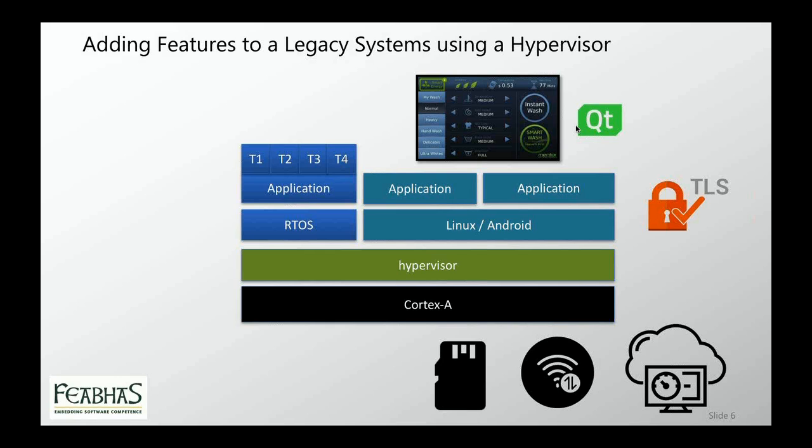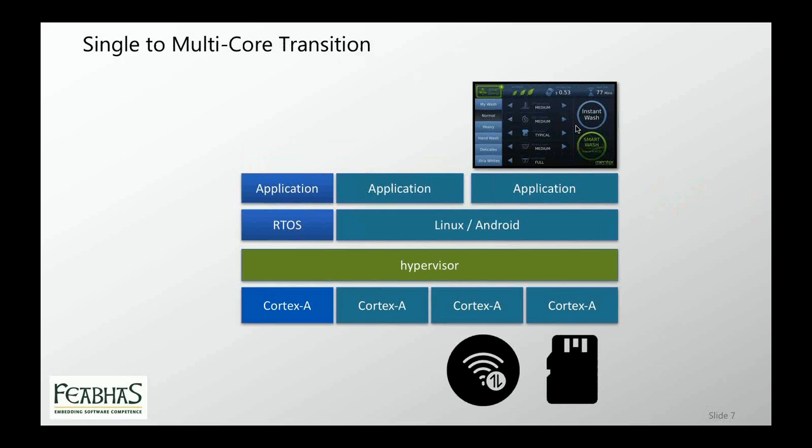The other area we've seen is the modern Cortex-A architecture, where only a few years ago I probably wouldn't have imagined using a multi-core system in typical embedded systems. With the modern power models these have become much more available to us. So where you think of only using a Cortex-M, Cortex-A is now a real option. And within that, the hypervisor technology also allows you to, for example, dedicate a particular core to the RTOS application.